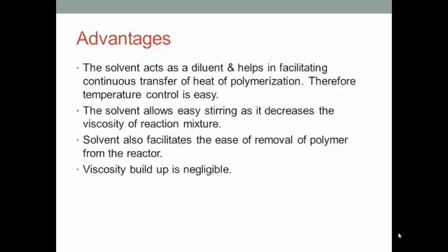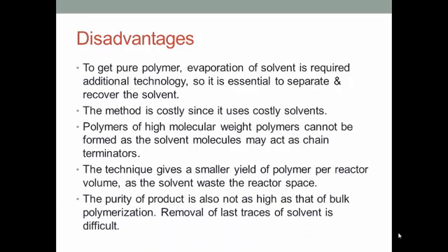And these are the advantages of this solution polymerization technique. The solvent acts as a diluent and helps in facilitating continuous transfer of the heat of polymerization. Therefore, temperature control is easy. The solvent also eases stirring as it decreases the viscosity of the reaction mixture. The solvent also facilitates easy removal of the polymer from the reactor. Viscosity buildup is negligible.